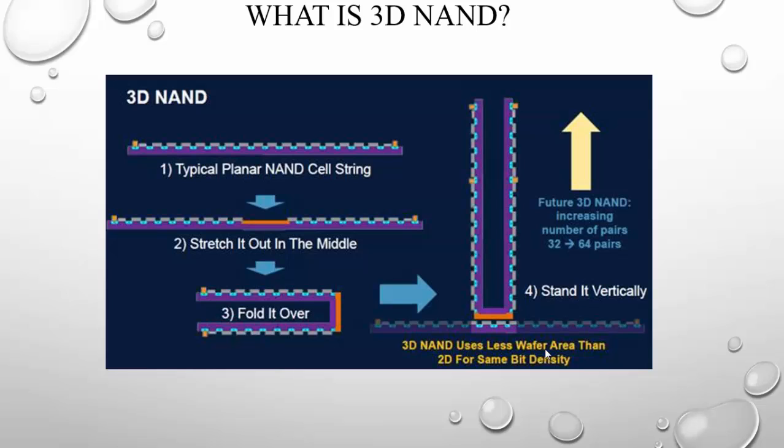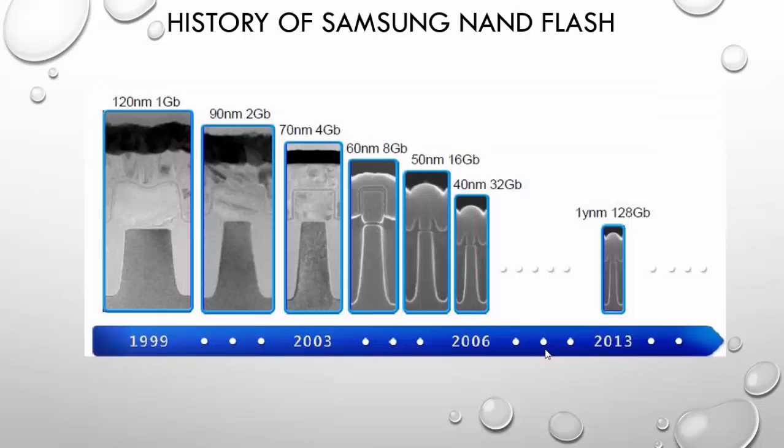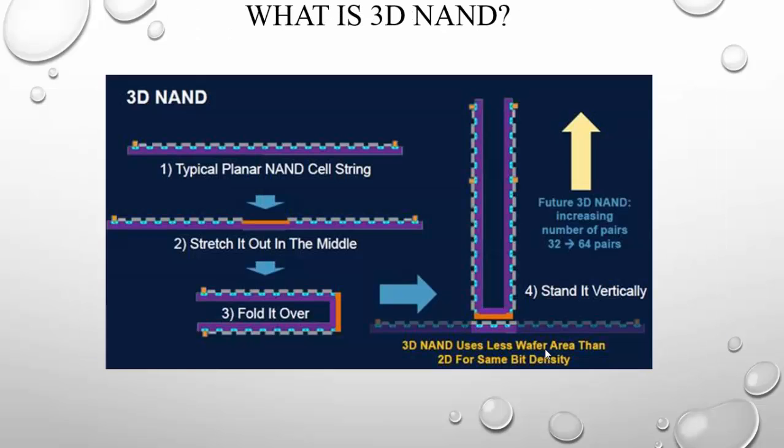Naturally this can be done by manufacturing NAND strings and folding them. Instead, the string is formed vertically using a completely different manufacturing process than is used for standard NAND flash. In fact, this is a technique that is new to all semiconductors. If you can lay down a horizontal series of control gates, then run a vertical series of floating gates and channel that respond to those gates, then you can build a string that may be several cells long in the same area as a single planar cell. So this is the basic 3D NAND technology.